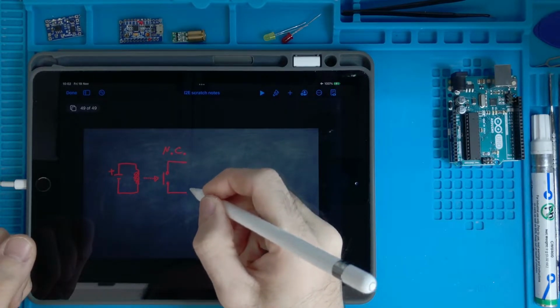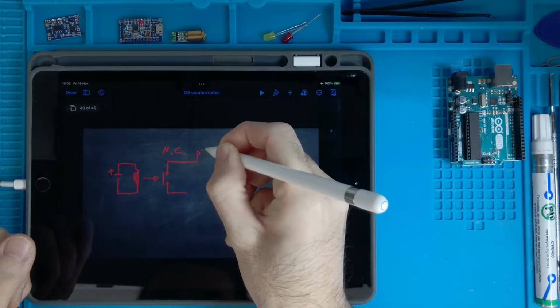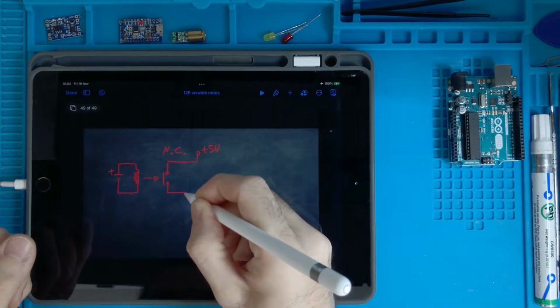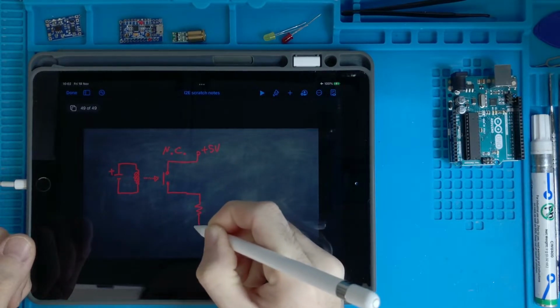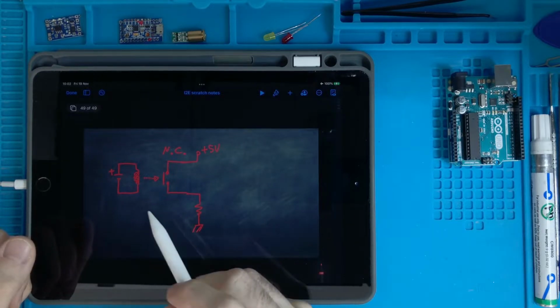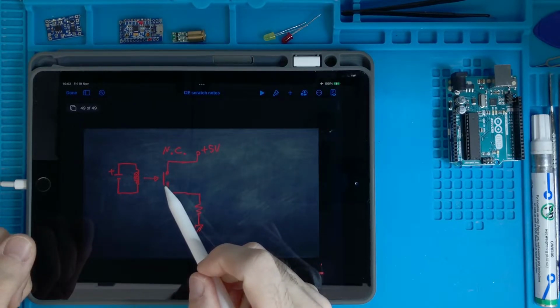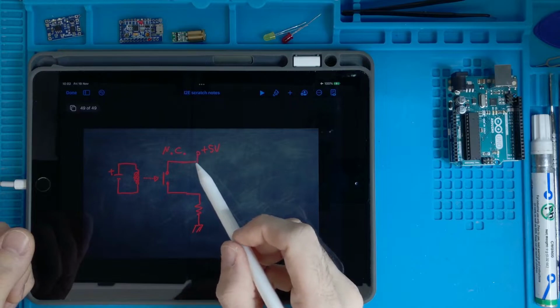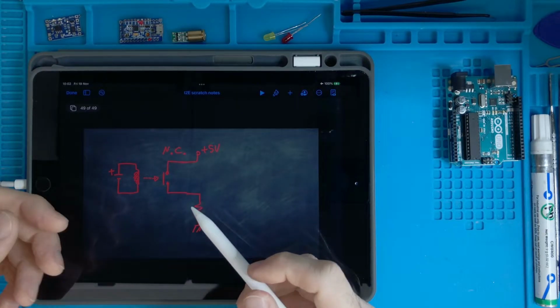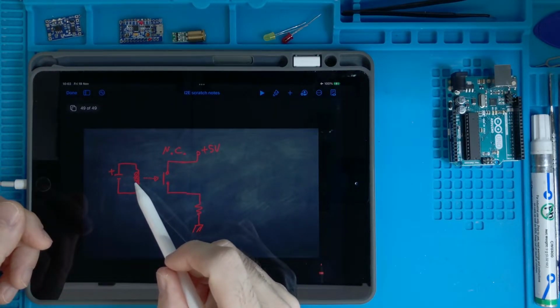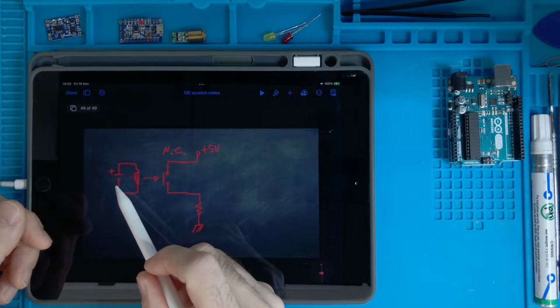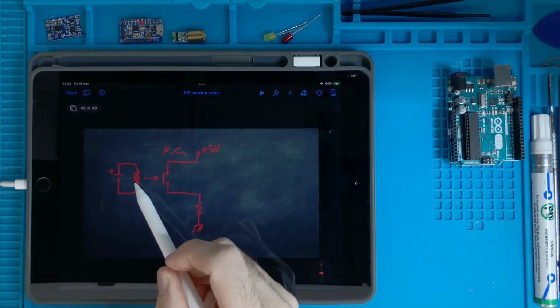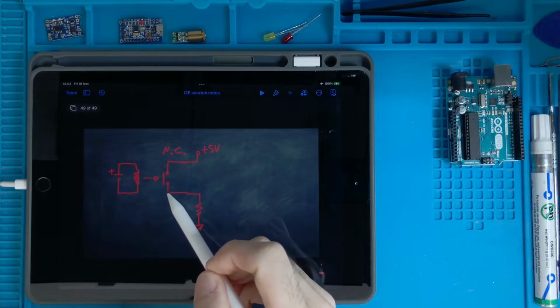Then if I connect it to a source of voltage, and then I put a load like this, a normally closed switch like this will create a current here only when this thing is deactivated, and if I activate the coil, then this will deactivate the output.